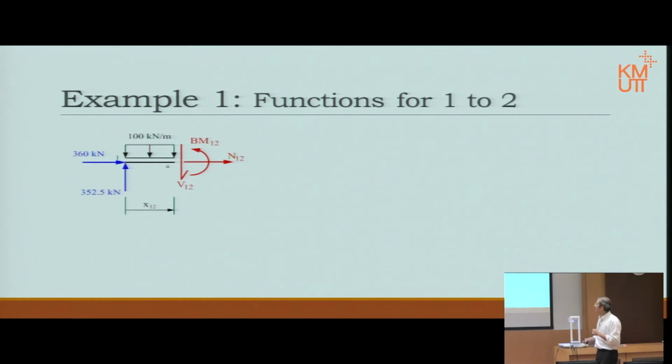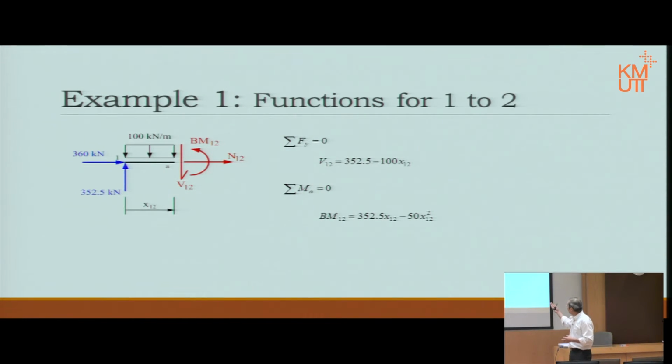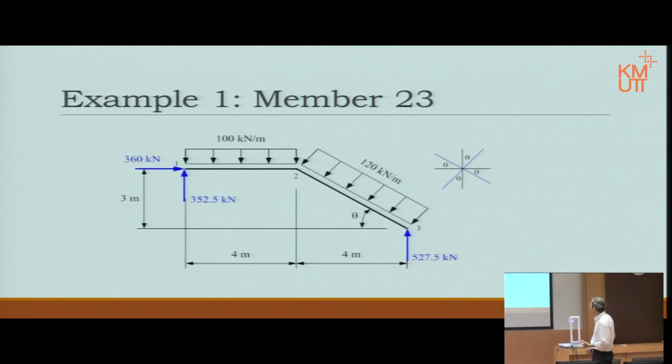Once we cut it, we have the usual system, three internal forces appearing. Sigma Fx, sigma Fy, and sigma moment would give you R. But since we already need the shear force and the bending moment, we therefore use only sigma Fy for shear and then sigma moment for the bending moment itself. Okay, once we get this, we keep it for drawing the graph later. Notice again that differentiation of bending moment is equal to the shear, but we have proved this before, right? And we also keep the notation there.